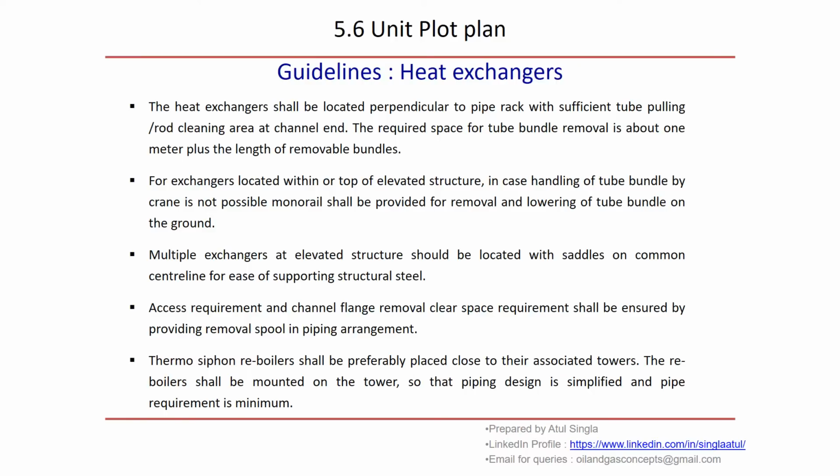Access requirement and channel flange removal clear space requirement shall be ensured by providing removal spool and piping arrangement. Suppose we have to take the exchanger under maintenance, we have to remove the piping, so for that we have to have some removal flanges in between. We open those flanges, we remove the removal spools, and we take it out for maintenance.